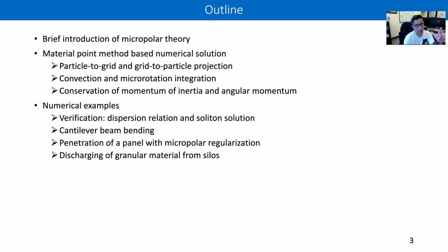And when we measure the difference between two points in the classical continuum case, we would lead to a Euclidean distance between the two points, basically the length. But in the micropolar material, because it has orientations, we also need to consider the curvature or the micro rotations that capture the different orientations of the material at different points.